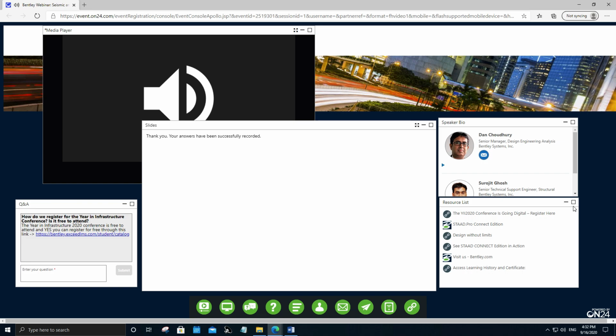So basically, in short, the answer is, if you want to have participation in the y direction, you need to see the modes where you have started getting the y direction participation. If it's over 20 hertz, then you consider that as a missing mass mode. The 90% requirement, as I understood from the code, was mostly for the lateral direction.